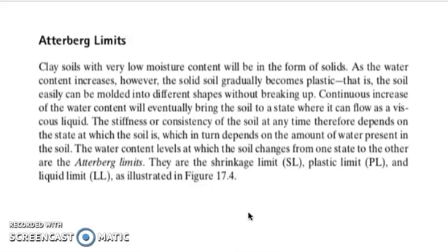We have to take note that for a clay type soil with very low moisture content, it will be in the form of a solid. As we increase the water in our clay type soil, the solid will gradually become plastic, and the soil can be molded into different shapes without breaking up.